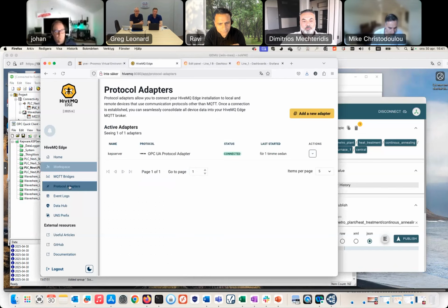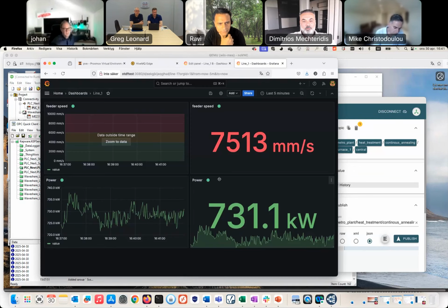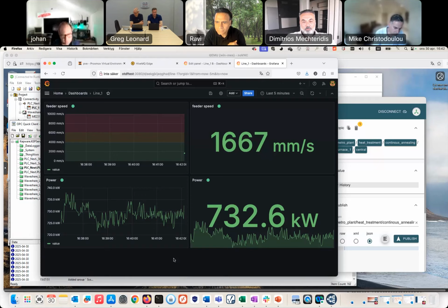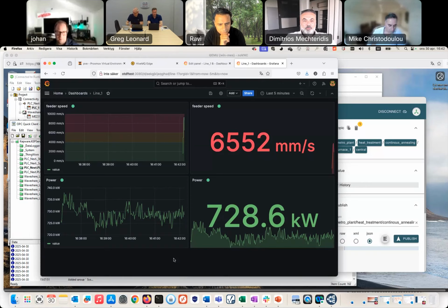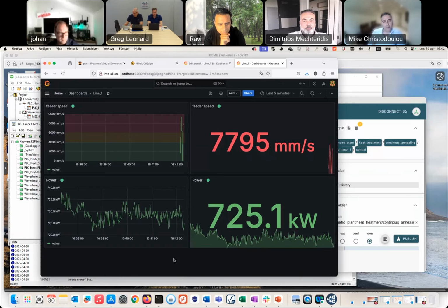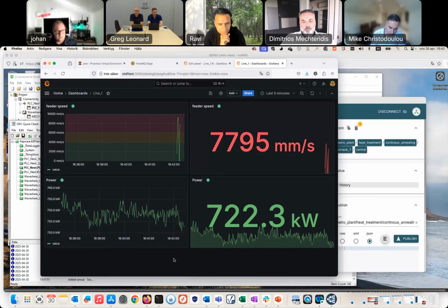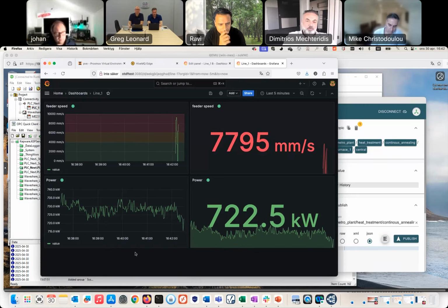And I will then rapidly move into the dashboard. This is a live dashboard being fed by my PLC behind me here. So when I move my lever, you can see that my measured speed changes. I have two data points here. I measure power consumption and I measure the speed, in millimeters per second. This is of course a made up case, but it shows you what's possible even on top of existing infrastructure today. We can build much more sophisticated things, but this was just to show you data collected in real time and visualized in real time.